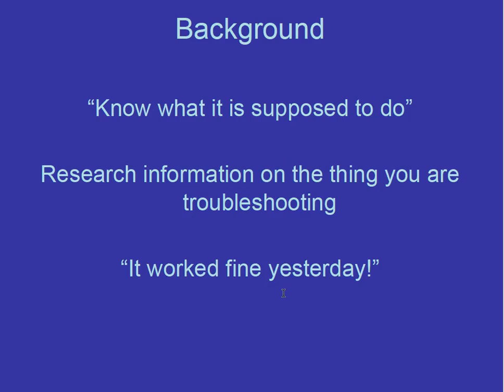So you need to ask yourself different questions. For example, what technical documentation about the equipment is available? How exactly is the equipment supposed to operate? Are there any previous lessons learned? Review any material history that exists for the equipment. Identify similar equipment to which you can compare the malfunctioning equipment. All these questions you should keep in mind as you begin to gather the information, and that will create the background of the problem.